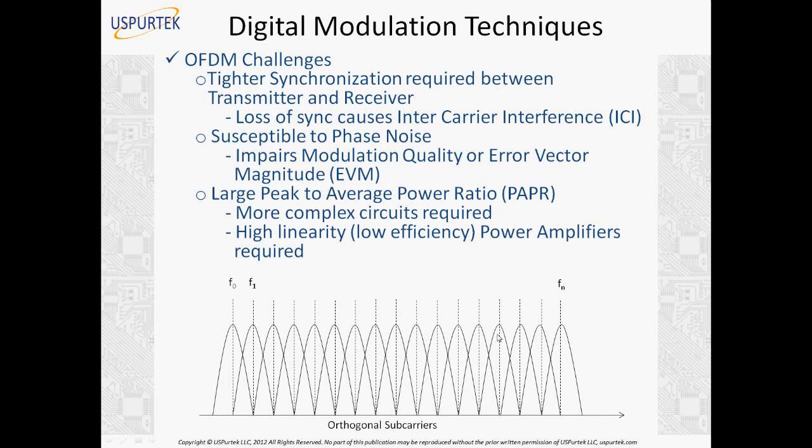So we have to deal with it. You have to clip the signal so that the peak power is trimmed down. So this is another challenge to be tackled when designing OFDM receivers. Well, a typical OFDM transmitter will look something like this.